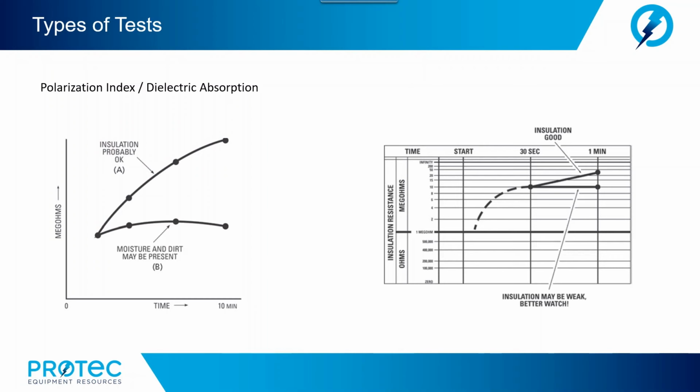References to typical PI values are common in the literature, which makes this test very easy and readily employed. Note that resistance readings alone are difficult to work with, as they may range from enormous values in new equipment down to a few megohms just before removal from service. A test like the Polarization Index is particularly useful because it can be performed on even the longest of cables, and it yields a self-contained evaluation based on relative readings rather than absolute values.